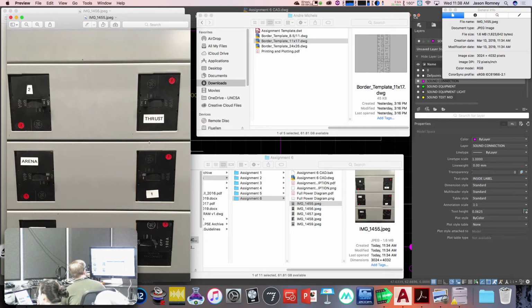And this panel has a bunch of these, say, 40 amp breakers on them. That's 40 amps times 3, because it's a 3-phase breaker. Which means if you wire it in such a way, you can actually get 40 amps 3 different times off that same breaker. But if any one of those legs exceeds the 40 amps, all 3 get tripped. But then there's also this 100 amp breaker that feeds a little service disconnect next to it that you can hook your own power distribution up to through some feeder cable, and that's 100 amps.